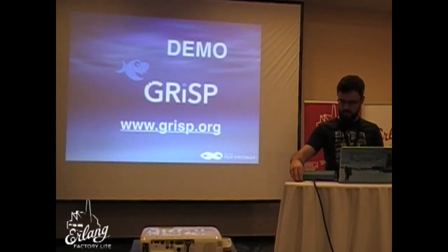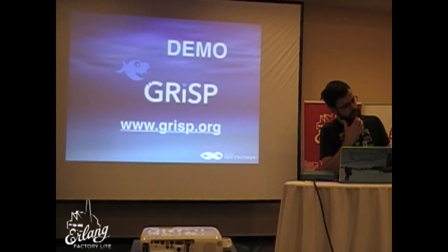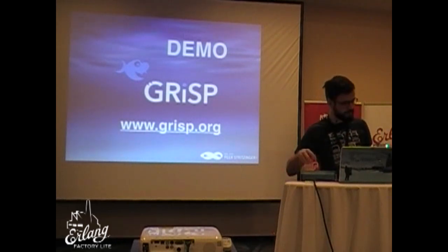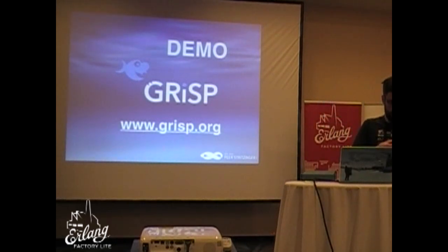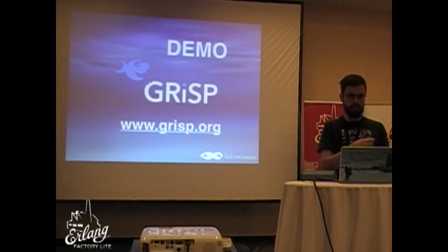So this first boot here just blinks, so I can reset it so you can see. It boots and then it tries to figure out something to boot, and then it's blinking red because I don't have an SD card put in. So I'm just going to put in a sample application that uses the LEDs. So this one will RGB cycle the LED. That's all it does. It boots and does this. But it's very fast. You can see it starts blinking the LEDs almost immediately after the reset button is pressed.